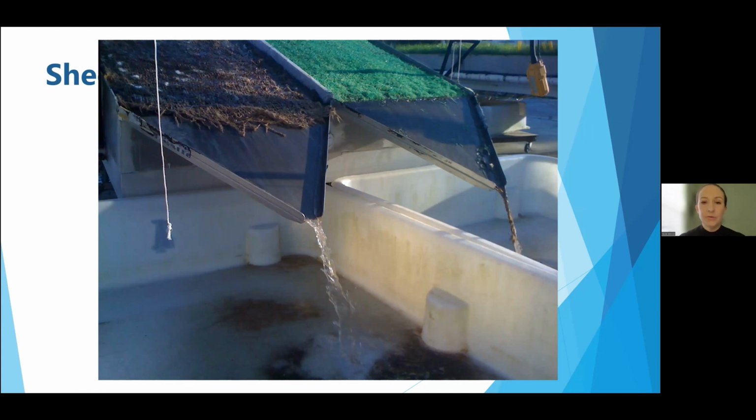The other thing we can do, and it's not necessarily considered a passive treatment application because it's a land applied application, is deal with turbidity sources that aren't coming in channelized flows. So if there are bare soils or sheet flow causing poor water quality on a site, we can also apply the polymer to existing mattings, which is what is here on the left-hand side. That's a polymer enhanced soft armoring, which is basically the granular form of the polymer applied to a fibrous matting. So that has two benefits: it works for erosion control.